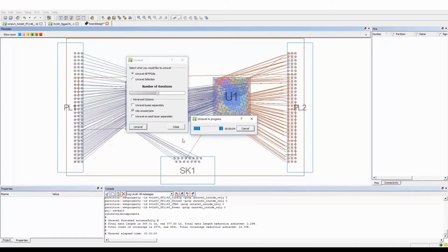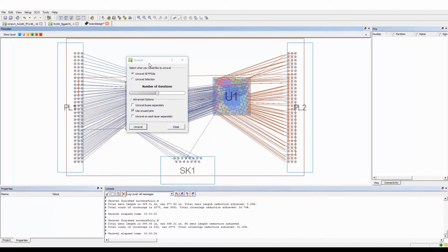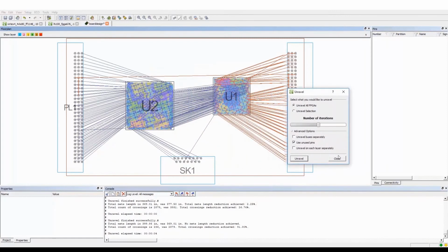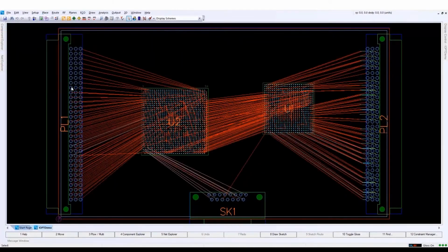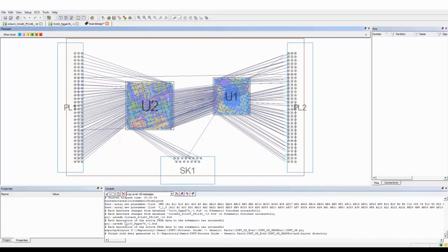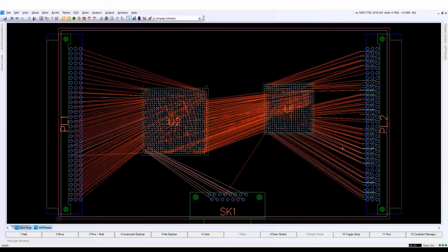Users can also make FPGA pin assignment changes to optimize routing. Early on, this can result in fewer netline crossovers. However, during the entire design process, the benefits can include reducing layers, minimizing signal integrity issues, shortening traces, and reducing the number of vias used.